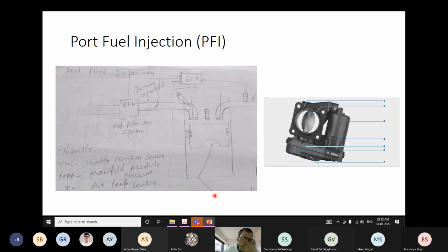So this is, in a very simple way, how I have explained it to you. In general, this is the basic logic through which the ECU is going to control the injector. But obviously, when you deal with actual conditions, there are so many parameters, like fuel composition, and so many signal conditioning units. So everything is going to be there, but the basic thing remains the same.